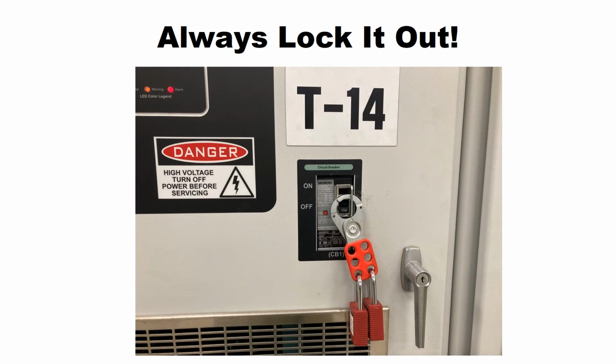Before I start talking about troubleshooting these circuits, I need to stress the importance of locking them out. If this circuit is energized while you are working on it, there's a good chance that you will be killed. It's that serious. You have to lock them out and make sure that the circuit you are working on is indeed the circuit you locked out.